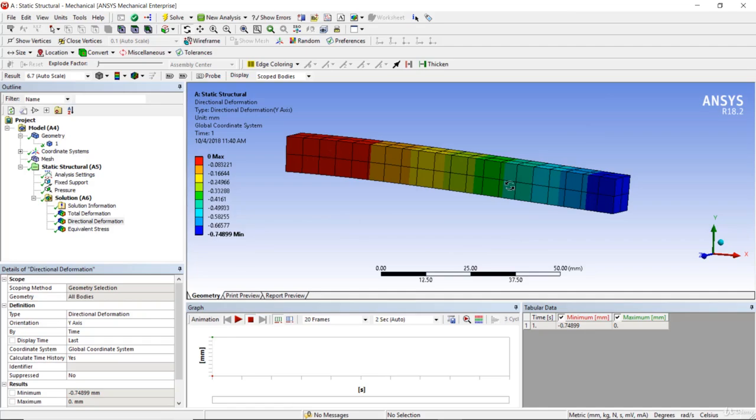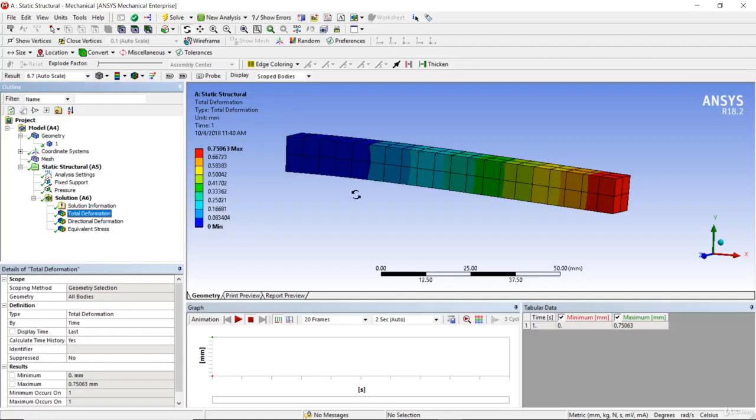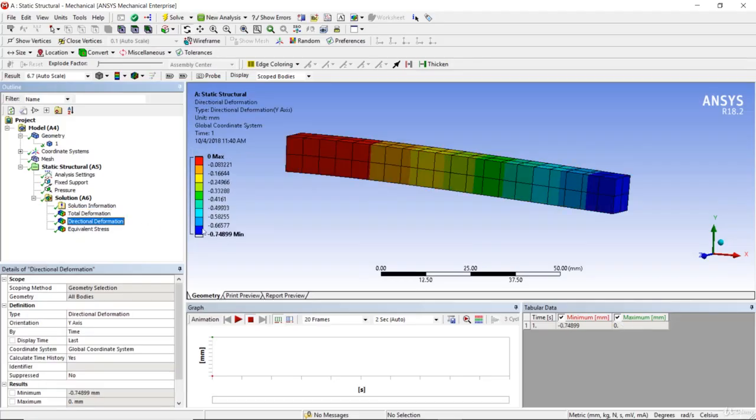And coming to the contours, in the total deflection, see, the highest deflection was represented by red, but here also the highest amount of deflection according to the software is 0, because if we take negatives, 0 is the highest number. That is why it is representing the highest value here and the lowest value in blue color. So as a CAE engineer, you should not go away with seeing different colors, and you should not be saying whether the component has failed or not based on the colors. You should be able to understand and interpret these particular results.